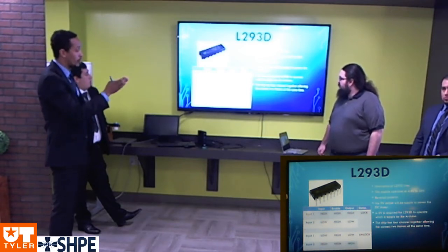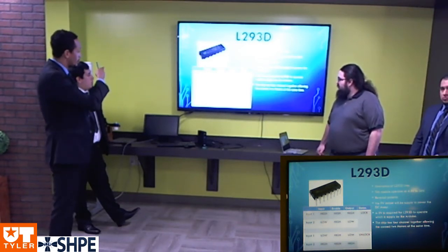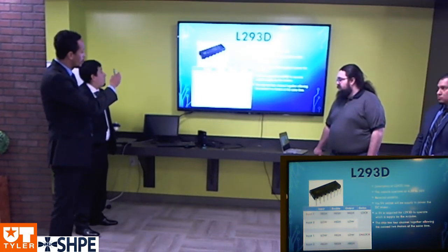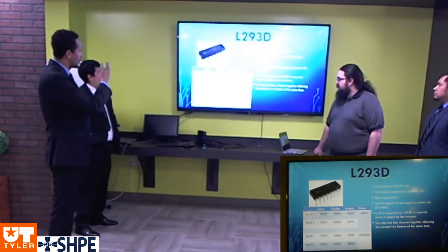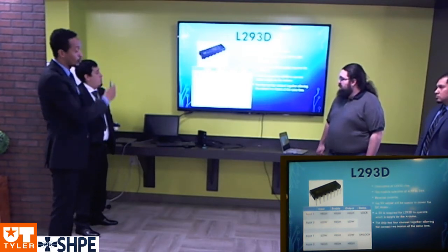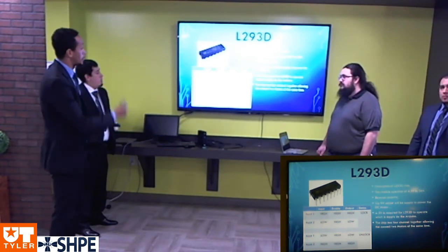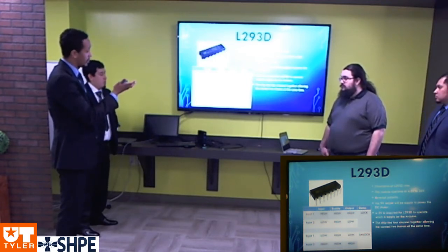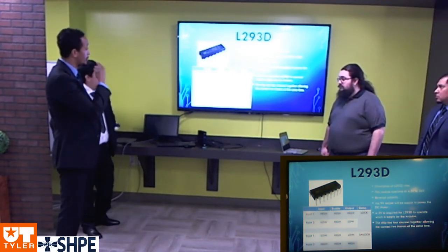So the door will lock in the same manner. When input 1 is low and the enable is high, it will go low, and then input 2 is high. With the enable high, it will go to unlock the door. And like I said, the chips run with 5 volts and it delivers a 9 volt to the DC motor.